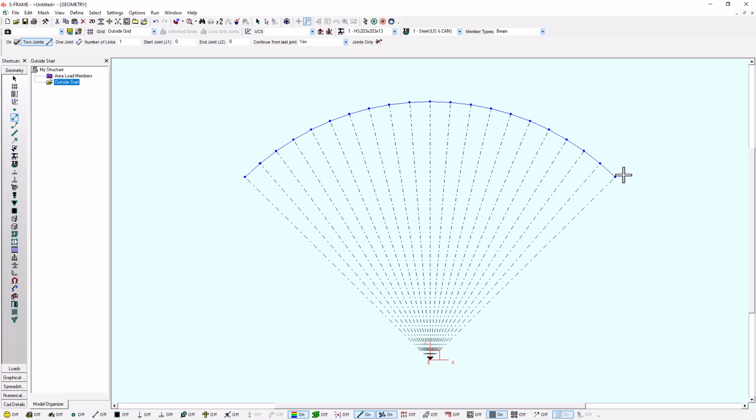And it's worth noting here that we can use the coordinate system origin and the clone tool to facilitate faster creation of this repetitive geometry about this type of pattern. I'm going through and showing you a few different options to work with. One of them being we can use the brute force method of drawing these members in, or we could be a little bit more intelligent with this approach, like we'll see later on, and actually draw in maybe one or two of these elements and then clone them about a pattern that we might want to use. I'm also going to update this folder here. So I'm going to say, let's just go ahead and update this open group with the selected content.